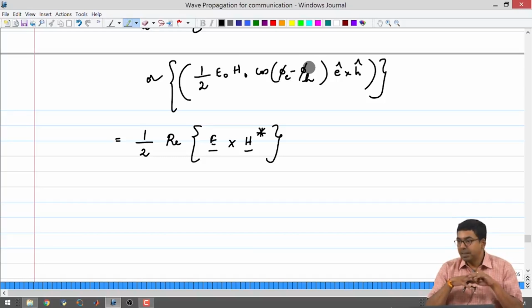In the case of a pure inductor, we know that V is equal to L di/dt, which means that voltage and current are out of phase by 90 degrees. More specifically, the current lags the voltage by 90 degrees in phase, and then when you take VI cos phi, you get 0. That means that your inductor cannot consume any power. There will not be a power transfer to a pure inductor.